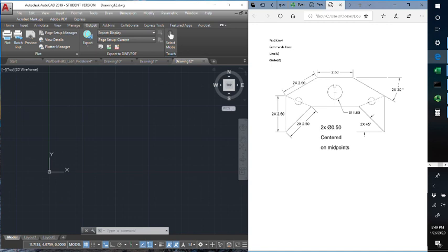Now here, this is more of that 2x thing I talked about, especially used in symmetry, and this is all symmetric. It's symmetric along the vertical center. And we can see that there's a 2x of this length, which tells me that this is also going to be 2.5. We can see that there's a 2x showing the angle from this line to the horizontal as 45 degrees. That tells me that that's also the angle that we see here. We see a 2x of 2.5 over here. That tells me that this is also going to be 2.5.